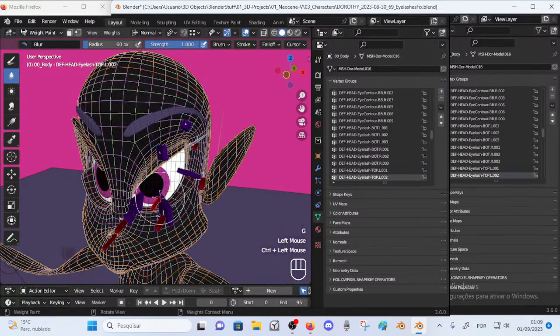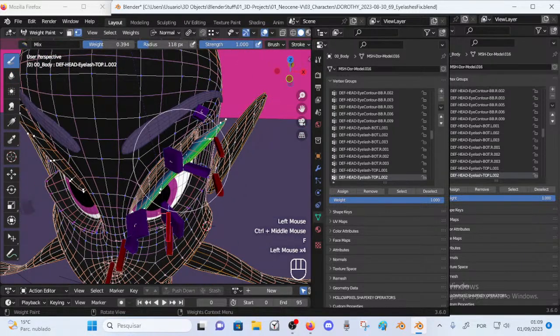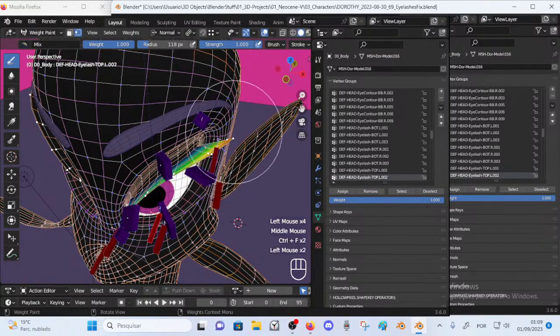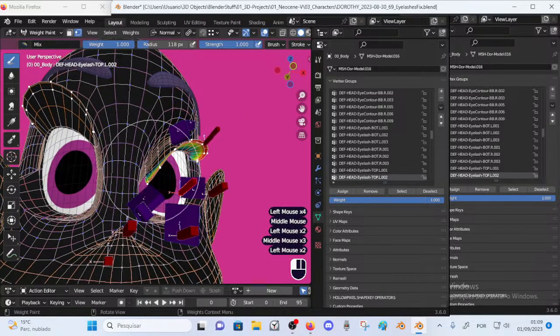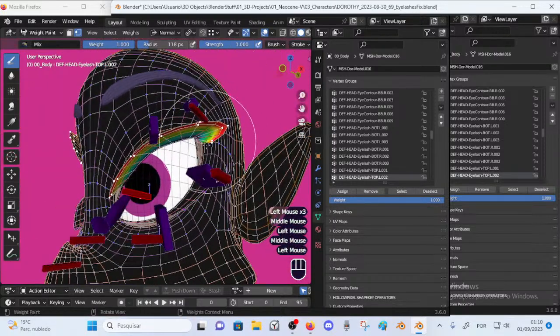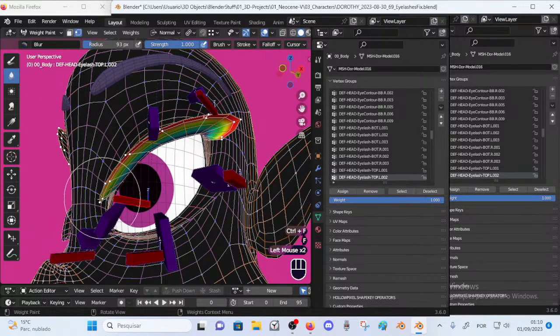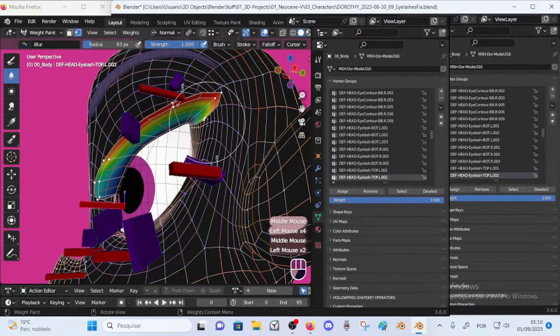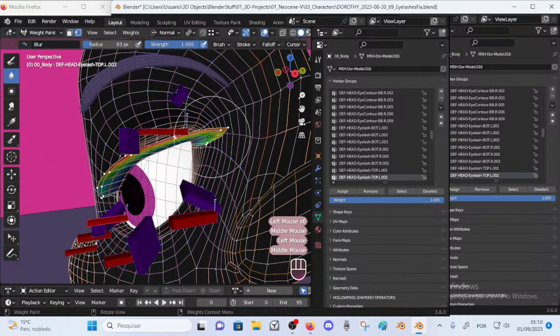But I haven't touched these waves yet, retouched this one, so let's try it again. I'll add now, because I'm not using auto normalize, I can totally do this without destroying what I've worked on on the other deformed bones. So I can just do this and then start to take off some waves on the extremities, more here, and same here. Oh, there you see, that was relevant to take off.